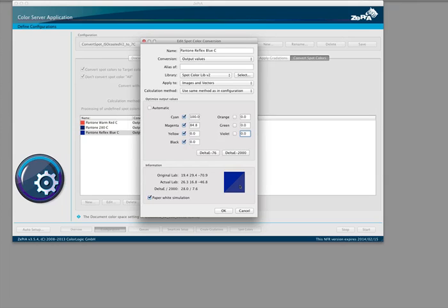So that's the reason why packaging customers tend to use more inks on press to be able to represent the different spot colors much better in their 7-color printing process instead of using CMYK. So using the automatic feature, you get a delta E of 1.0 delta E 2000, which is a good match.